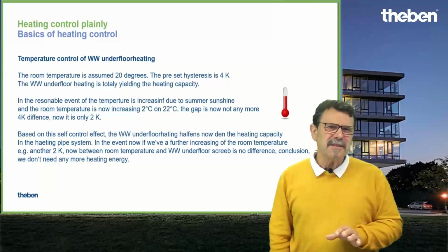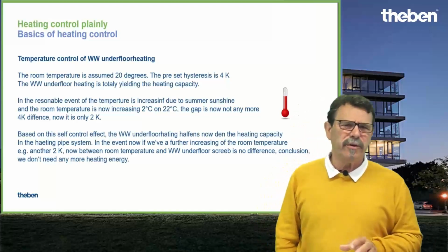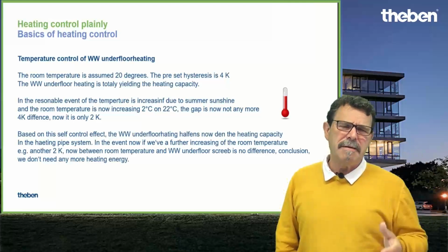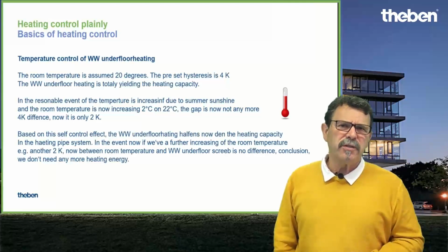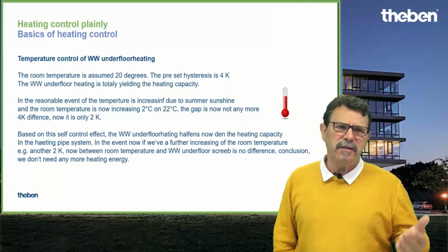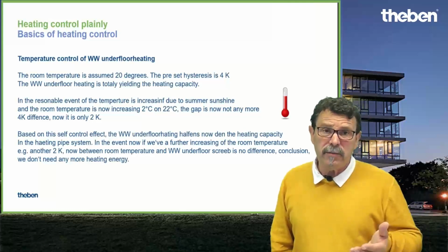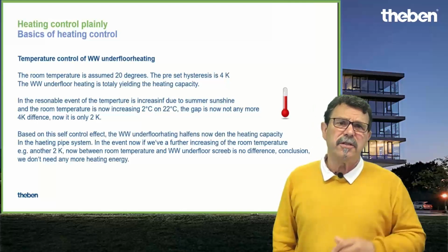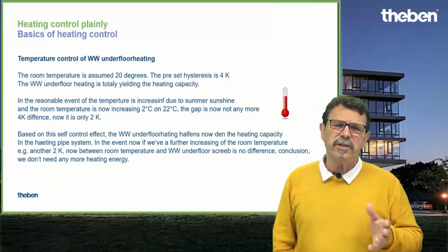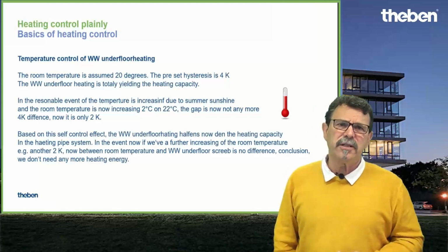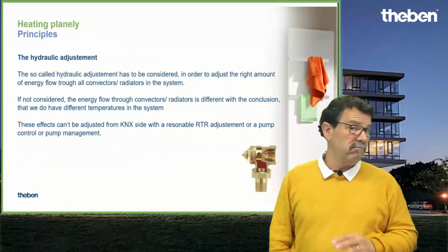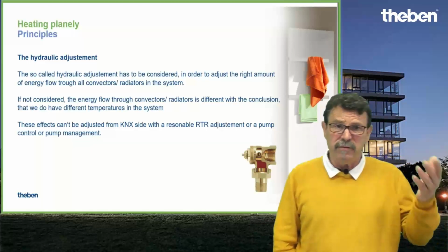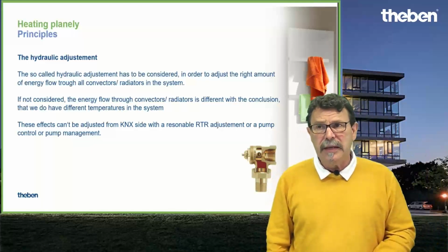Otherwise it is not that efficient anymore, because it always depends on the screed and the insulation we have. When we reduce the temperature too much, you need a long time next morning to heat up the system again, and so the energy efficiency is not that good. So 1 or 2 degrees maximum night reduction, that's it. A recommendation from more than 25 years of experience.